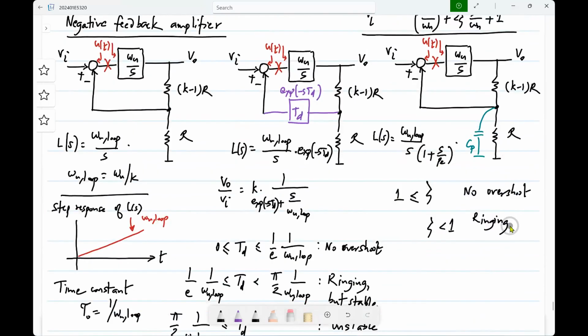So as you change the value of zeta, at some point you have that repeated pole case, and if zeta is lowered below that, the poles will split into complex conjugate parts. You can do the exact same thing here. Essentially you find the zeros of this denominator, and if you look for the condition where you have only real poles, you will get that same condition.